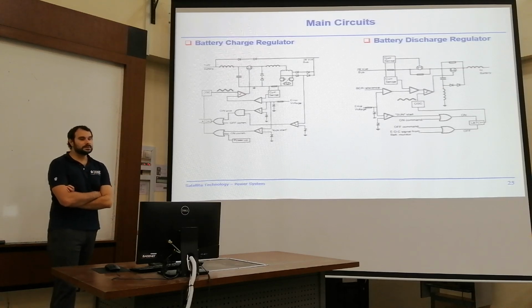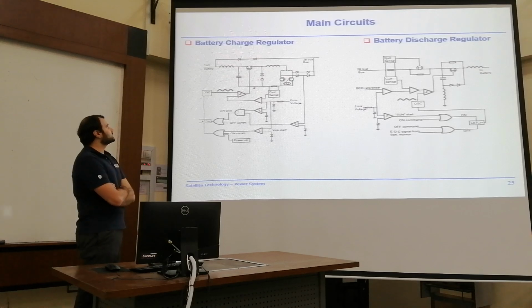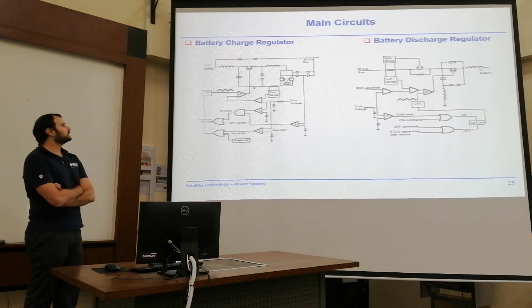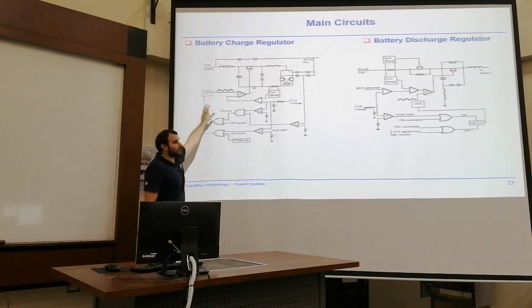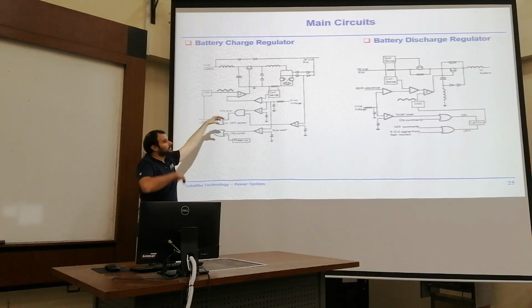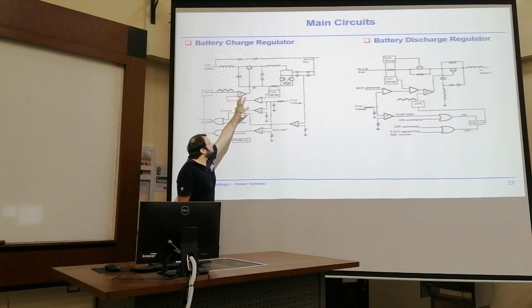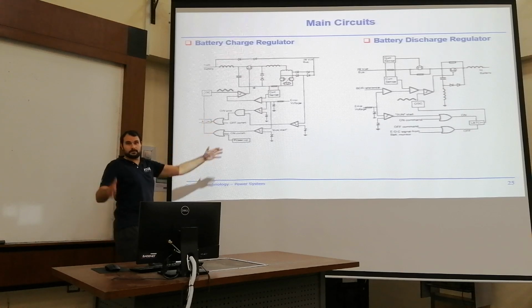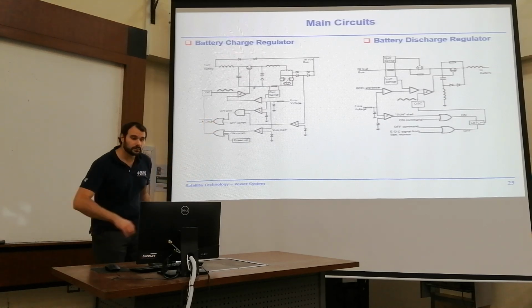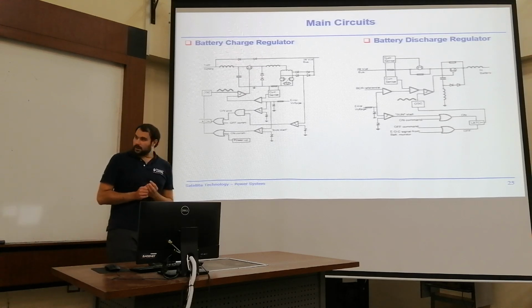And for the BCR and BDR, they both use very similar concepts, and I think we don't need to go too much into detail. Just remember, it's an oscillating process. You have an oscillator, and usually you would also have an electronic switch, like a MOSFET, and some filtering, and for sure a big induction coil to stabilize the voltage.